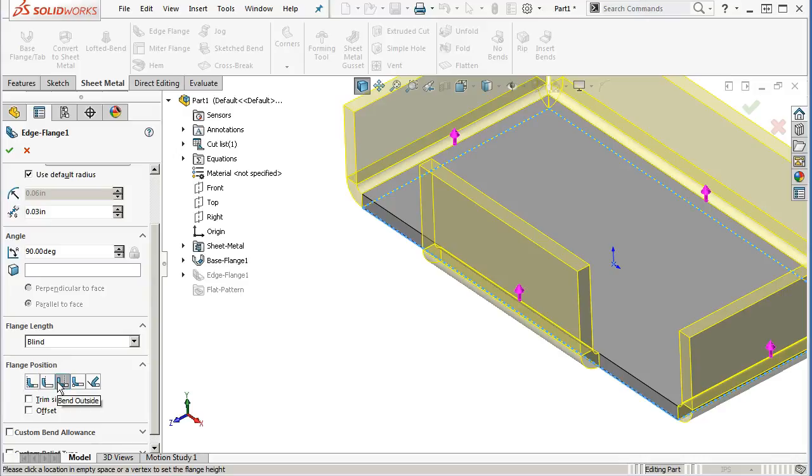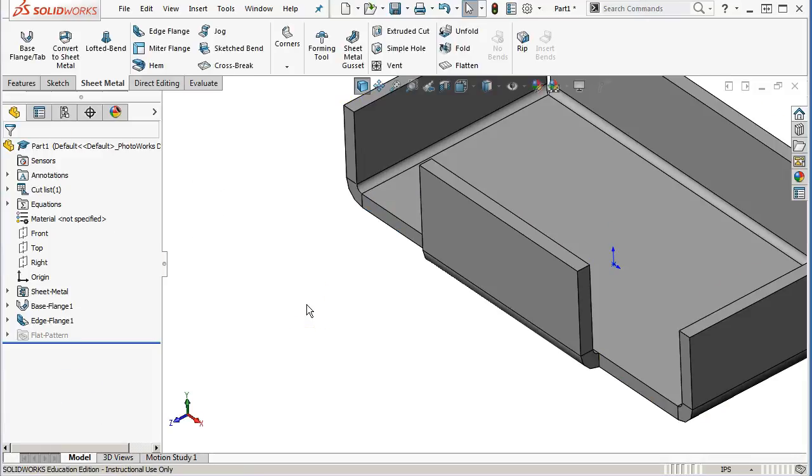That's my preference. In some condition like this, I would shrink this so we have a 0.13 radius, or 0.06 radius, with a 0.13. I would go into that base flange sketch and make it 0.38 smaller, if I'm doing the math right, so that I would end up with the outside of the box 2x4. So I'm not doing that calculation or driving some of that internal geometry, staying to the outside. Right? But it's a matter of what equipment you have available.